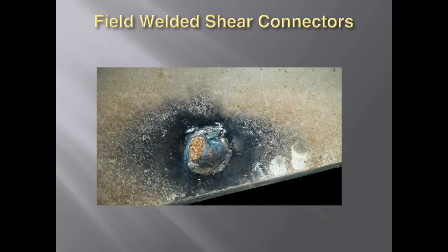The other thing during the stud welding process is to make sure that the stud welder is grounded to the work surface in an area that is not a primary member. So typically we like to see them on a cross frame or something like that, so that if it does short out, it's not going to cause any damage. This was actually on the bottom flange of a girder.